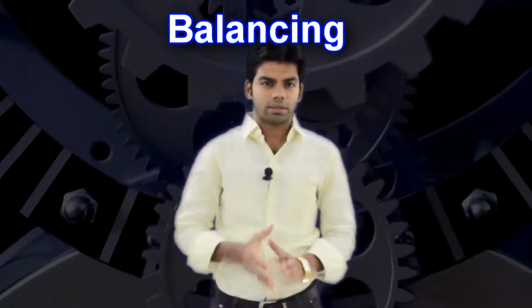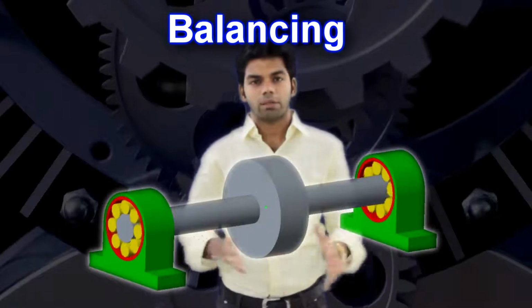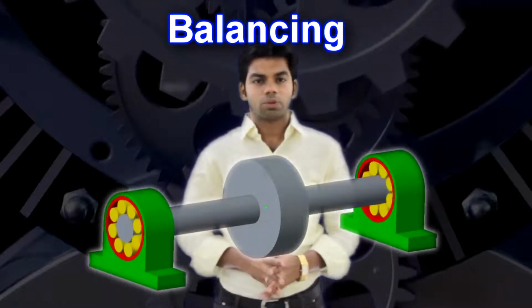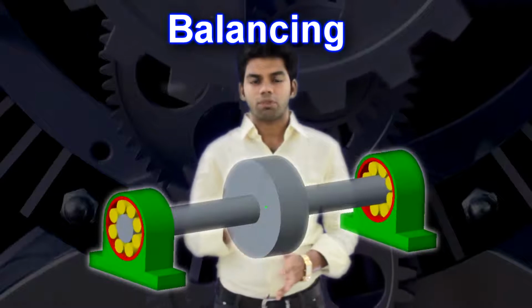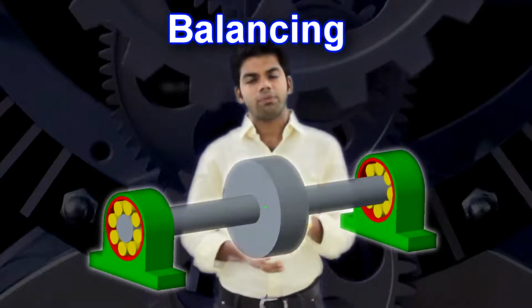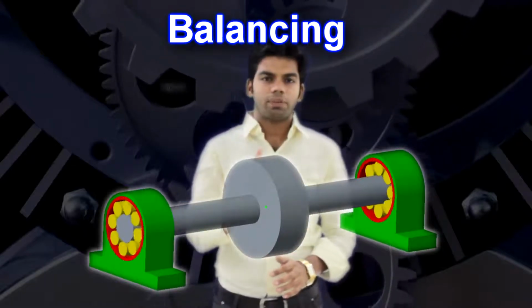Now let us first consider this case. Suppose we have a rotor which is rotating on a shaft supported in two bearings. If the center of mass of this rotor coincides with the center of rotation, the axis of rotation, then we can say that this component is a statically balanced component.